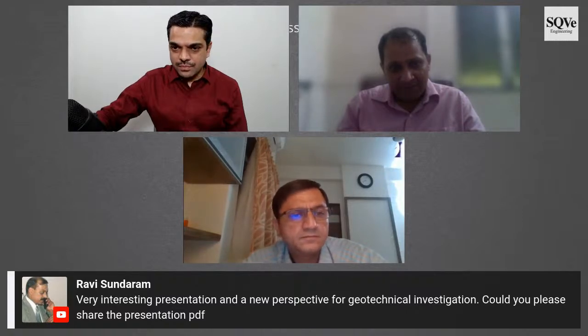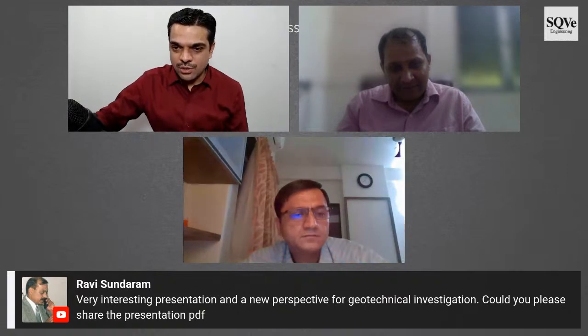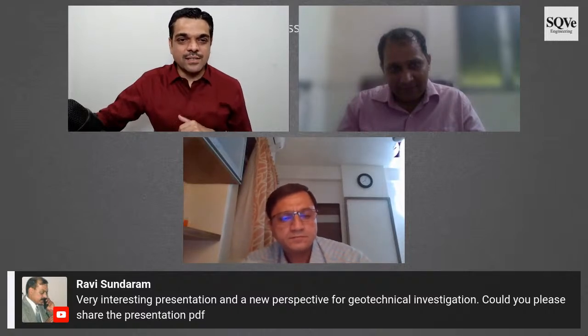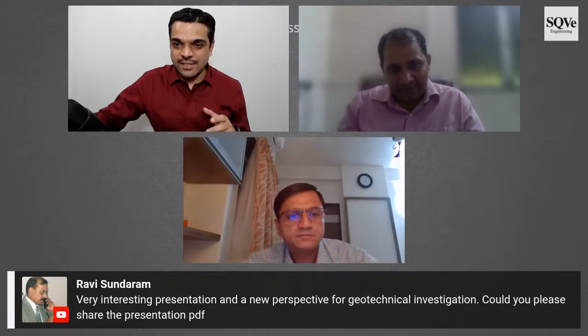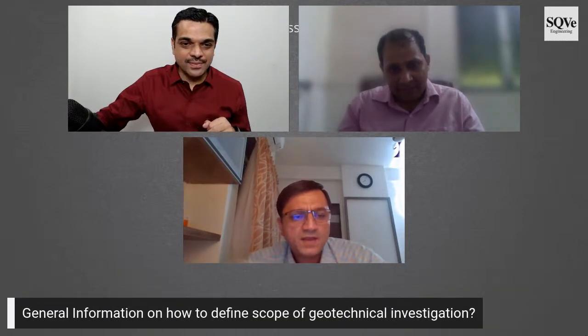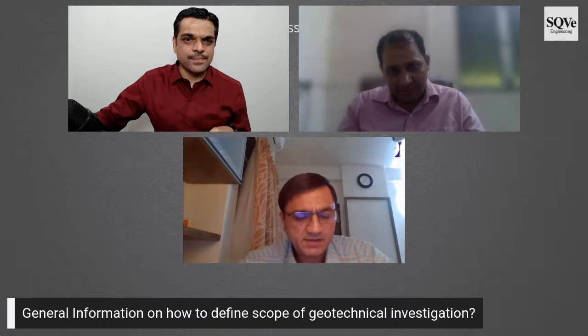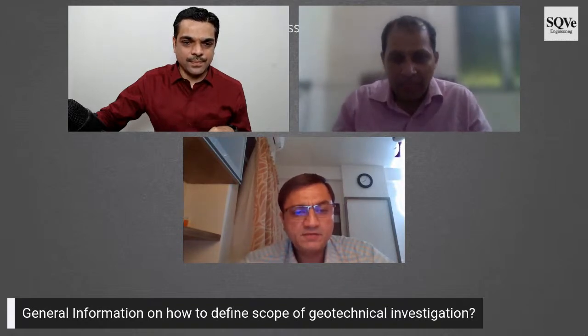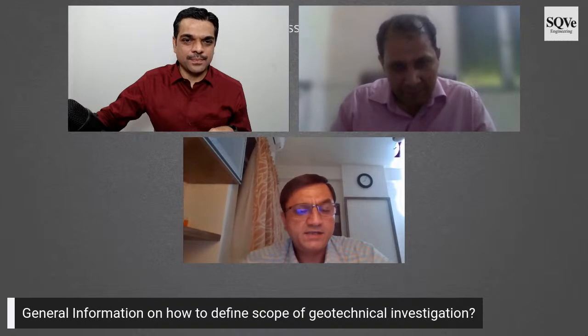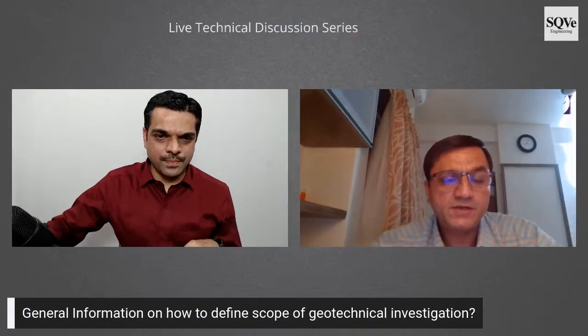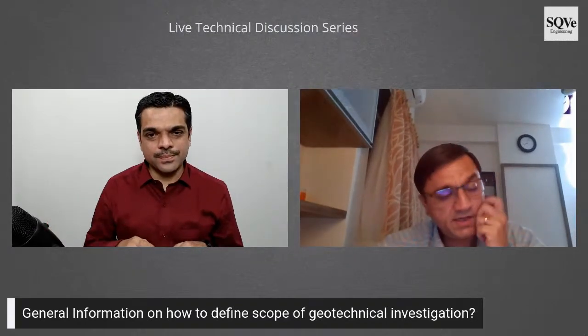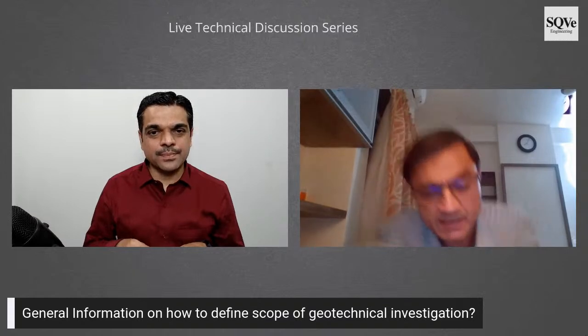Okay. So can I go to Dr. Jay Kumar Shukla: in his opinion, what will be the general approach for deciding the scope for geotechnical investigation? I would say that should be based on the type of structure, the extent of the area which needs to be investigated, and then the intensity of loading which you need to transfer from your superstructure to foundation. So usually it is recommended that we need to have a two-phase investigation.